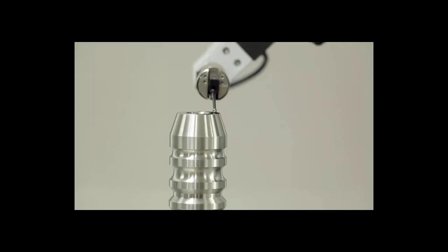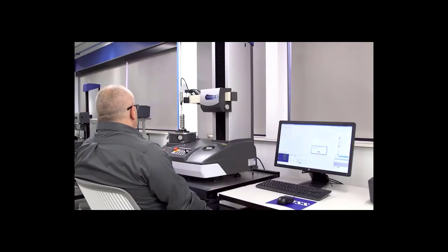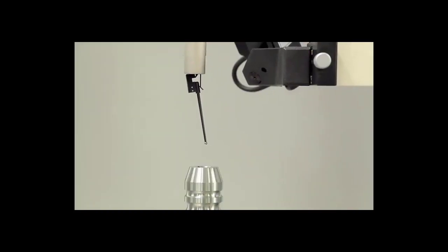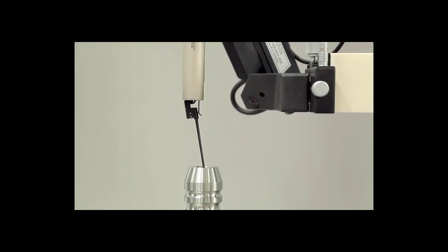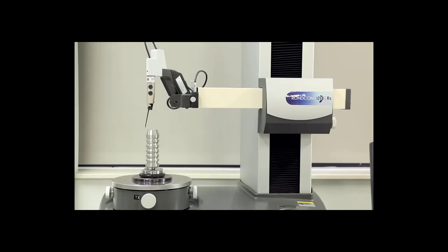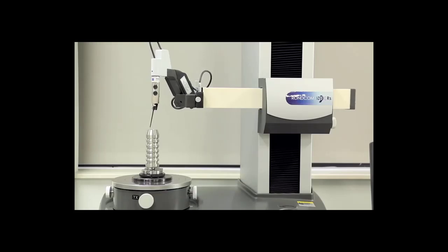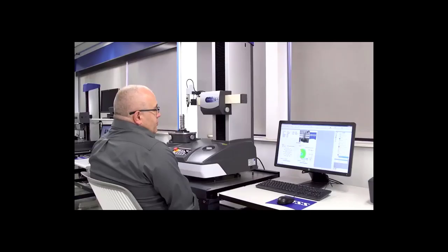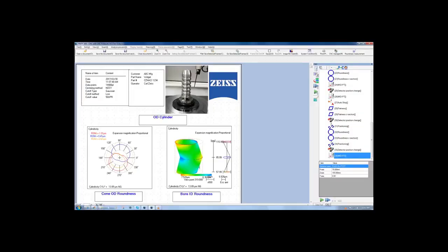From here we're taking a flatness trace on the top of the workpiece, and then we move to the inside and do an ID measurement. The mp4 software comes equipped with the latest standards and settings for form and finish measurements. mp4 also has the ability to find edges of workpieces to form a part coordinate in R or Z axis. From here we will move back to a safe position, the load/unload position, for the operator to load the next workpiece. Upon completion of our measurement process in the CNC program that we have selected, the report is automatically generated. The reports are fully customizable.